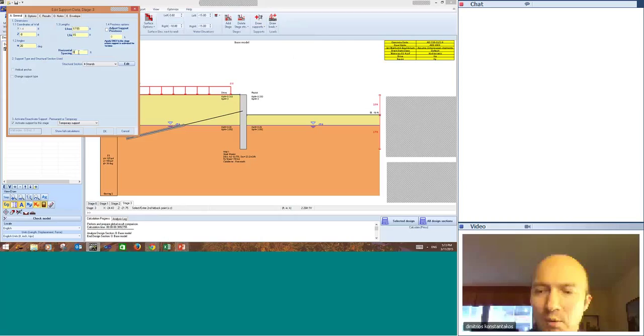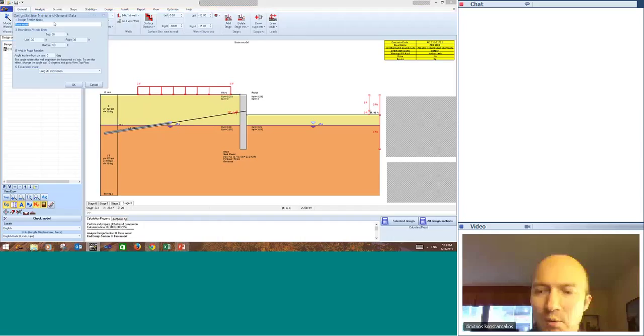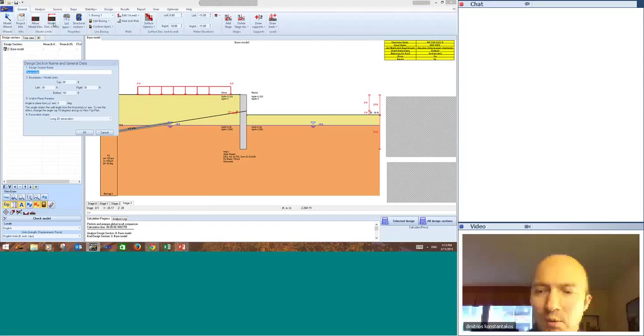And let's put a spacing of 7 feet here. Next, we can put a pre-stress, let's say 55 kips. We're guessing something, but we'll find that number out. And the reason I'm putting a pre-stress is because we're also going to do a nonlinear analysis. Now we're seeing that the tieback falls here, so that our model is not sized ideally. So what we'll do is I'll click on the model dimension limits here, and I'll change the left coordinate of the model to -60.